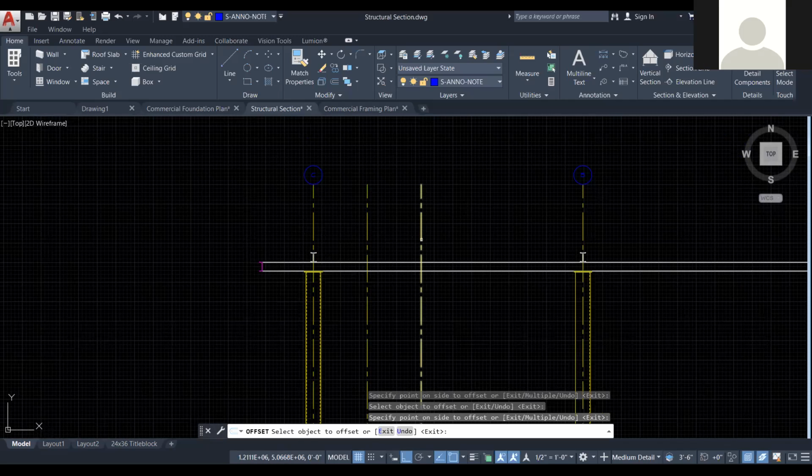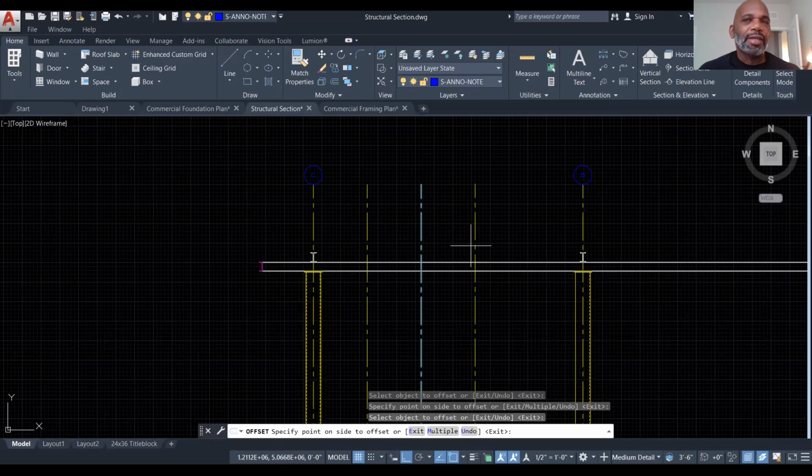And it looks like there's a single ply roof membrane on top of the insulation, and that's just going to be a line. So what I want you to do is, above the insulation, give me about a half of an inch space. It wouldn't be a space there, but we put a space there for architectural license, so you can tell the difference between the actual single ply membrane and the insulation.